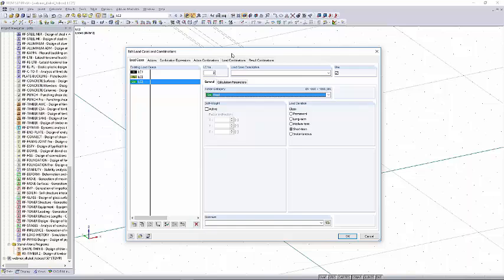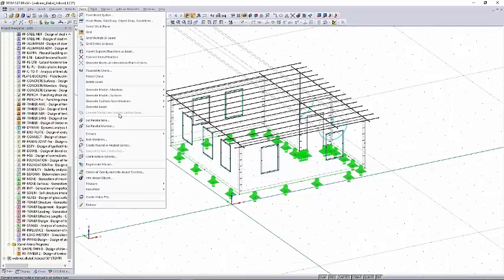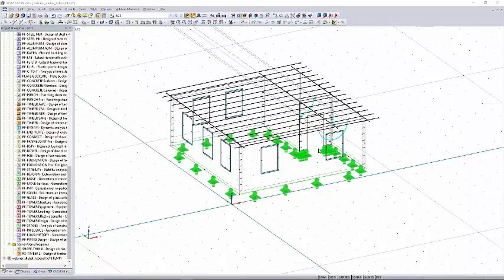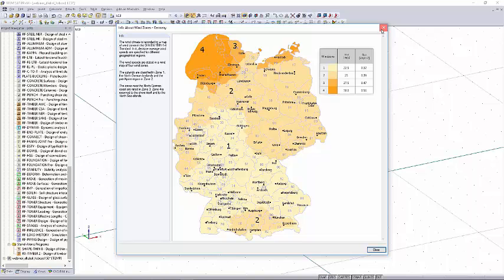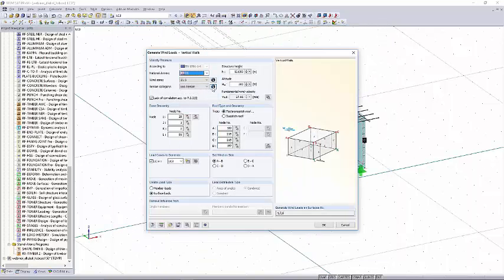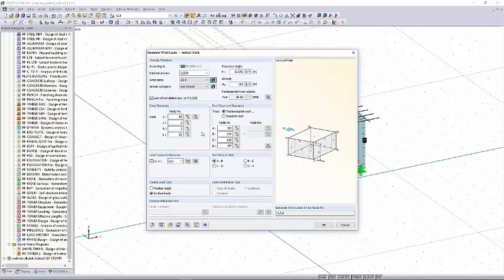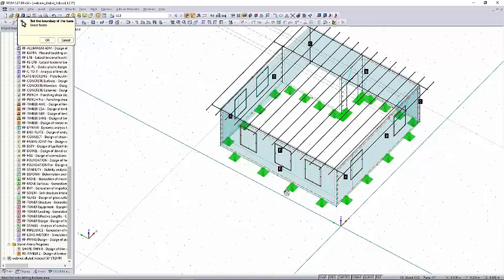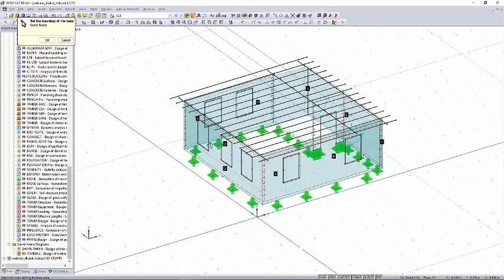There must be, even on such a structure, 8 wind loads generated according to Eurocode, but now I will calculate this 1 load case. It goes with the same intelligence, vertical walls. It has also the same norms, all the things that I said for the snow load count here as well. Oh wait, I was in Germany here, hold on. United Kingdom, wind zone, and well, there's probably some more wind in the United Kingdom than here. So now it is important from which side you start to pick the nodes. That's why I do it one more time now, just to show you how it works.